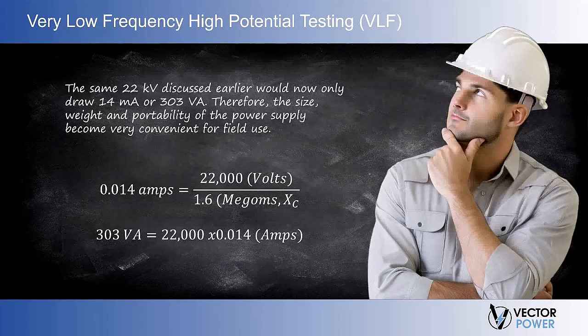Now, we further do the mathematics and we see that the power supply VA requirement has been significantly reduced. Thus, the main advantage of testing at very low frequency is that it significantly reduces the size, weight, and cost of the required power supply, and thus offers greater attraction for field testing of medium voltage cables.